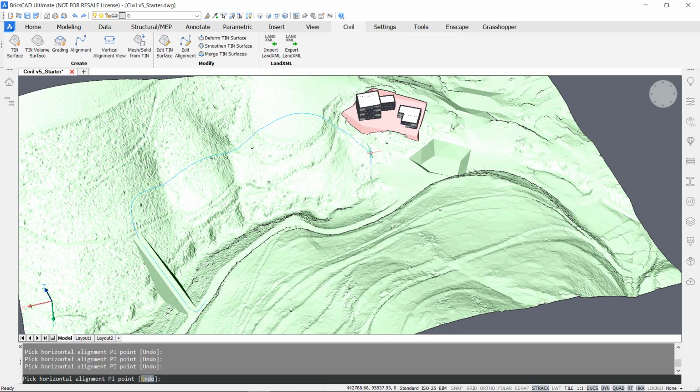And then just along the building path a little bit. It can go over this depression part that's not like this, for example, and then I can press enter, and then I can pick an origin point for the vertical alignment or for automatic 3D alignment. So I will choose the automatic 3D alignment. So I type in A and press enter.